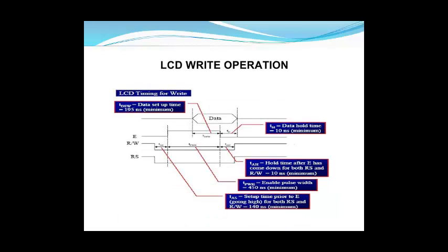Similarly, we'll have a look at the LCD write operation's timing diagram. As we can see, whenever the enable pin goes from high to low, the read write pin is low, and the register select pin is low, the LCD write operation is performed.